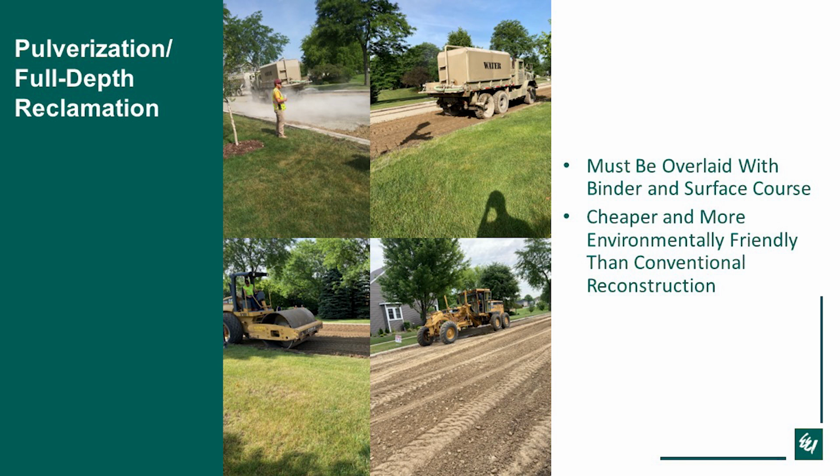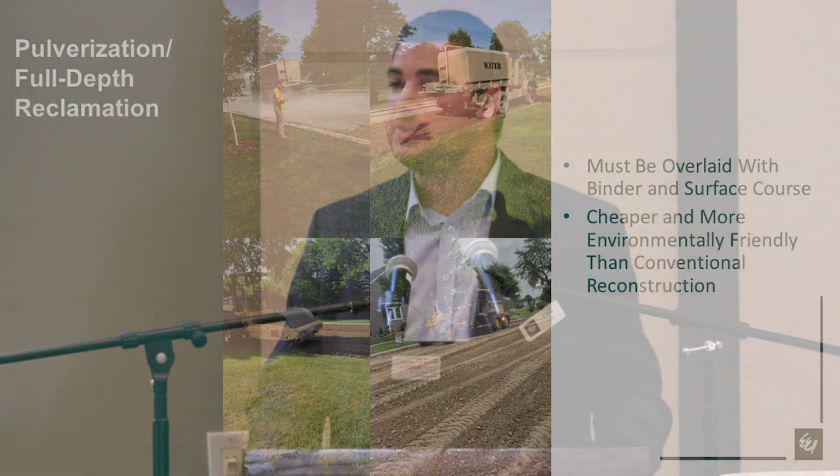In this case, it was existing aggregate base course and pozzolanic base that got ground up and then put back down, and the cement and water got all mixed together to make a new material. I see. So that's what that picture that's getting graded is showing. That's the new base that's being used. I see. Okay. That makes sense.